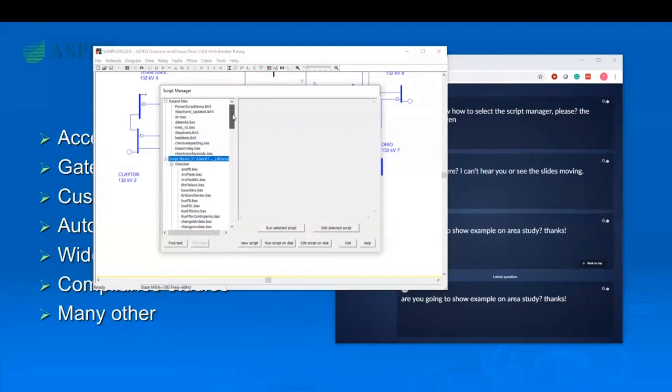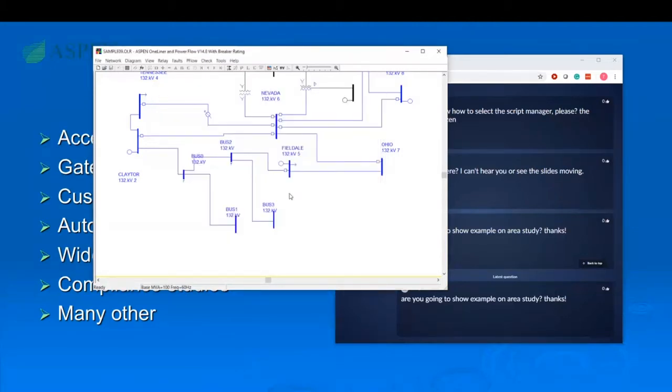Okay, so I'll try to highlight a few here. First one, one of the very important tasks that a protection engineer has to perform before setting the relay is to find out if the line is short or long in terms of electrical feature, and the indicator is calculated with a parameter called source to line impedance ratio, SIR.